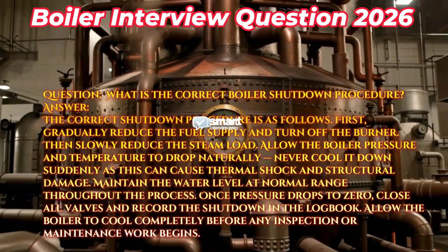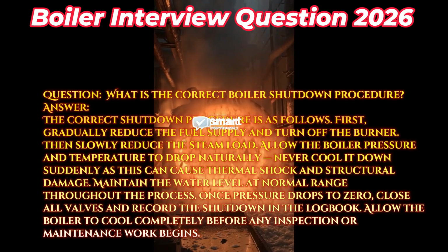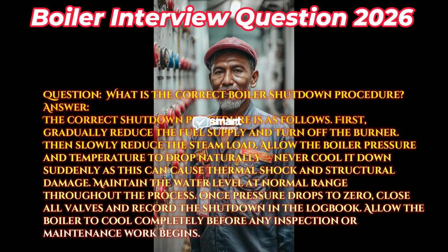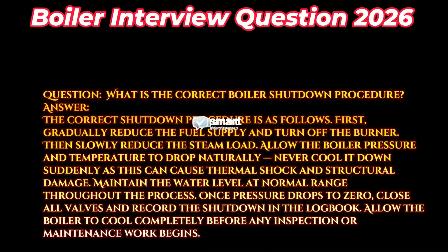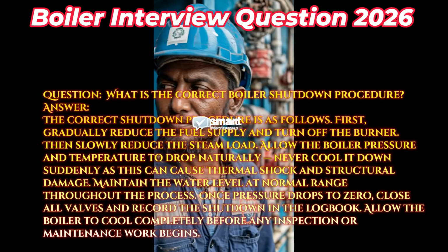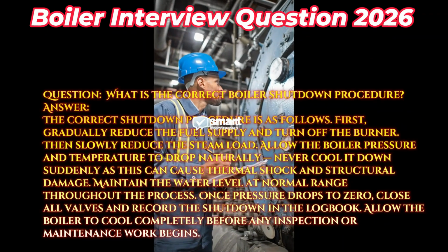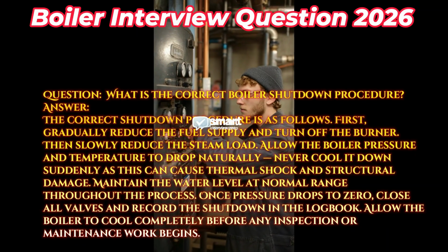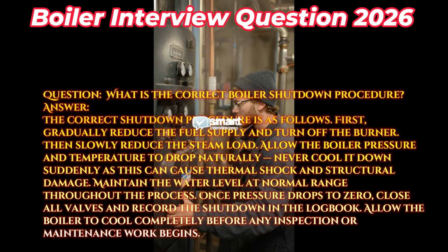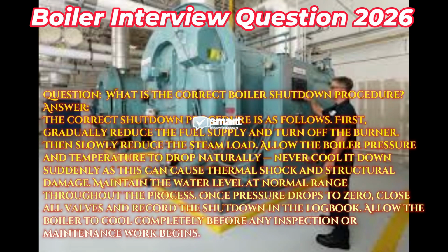Question: what is the correct boiler shutdown procedure? Answer: the correct shutdown procedure is as follows. First, gradually reduce the fuel supply and turn off the burner. Then slowly reduce the steam load. Allow the boiler pressure and temperature to drop naturally. Never cool it down suddenly, as this can cause thermal shock and structural damage. Maintain the water level at normal range throughout the process. Once pressure drops to zero, close all valves and record the shutdown in the logbook. Allow the boiler to cool completely before any inspection or maintenance work begins.